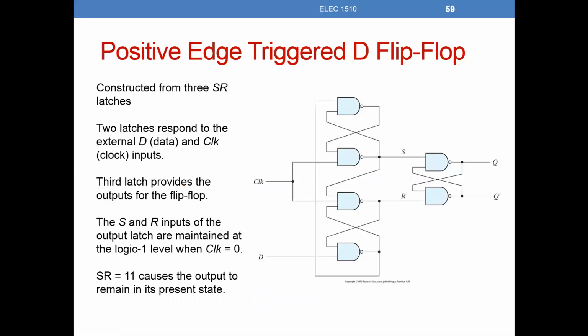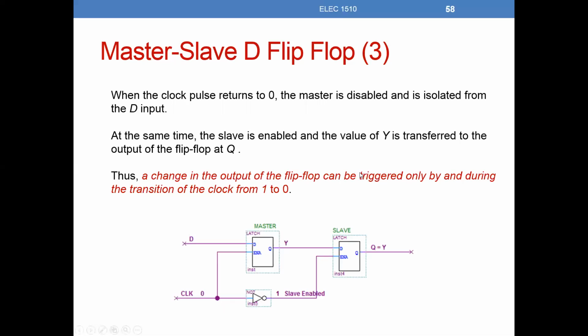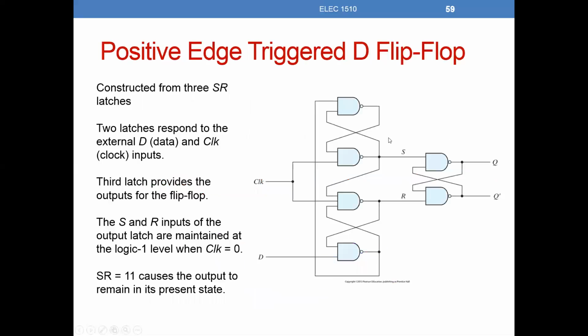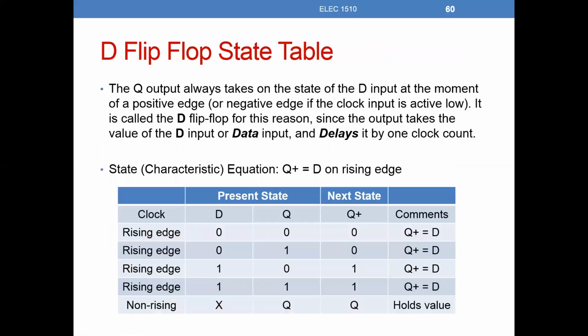All right, so we're now going to draw out something that looks like this. This positive edge triggered flip-flop once again goes back to the set reset latch, right? We end up with a clock coming in here. This is all made out of NAND gates. You can see we have a few more gates here. Then feeding back, we have our data latch down here. Remember, our problem with SR is that the 1-1 with the NAND gates caused an indeterminate state. It caused Q and Q not to be the same value, right? Well, this configuration eliminates that problem.